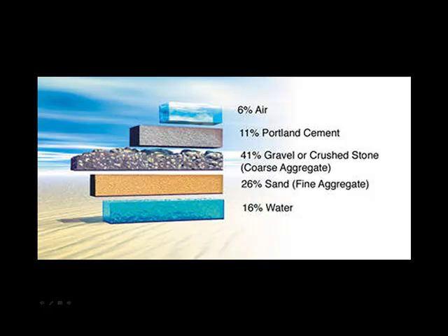Now, while I enjoy the look of this graphic, I would be very cautious about the percentages of the various ingredients. I'm not sure I agree with that at all. They show 16% water. I think that would be a very weak mix, and I believe a good mix requires much less water than that.